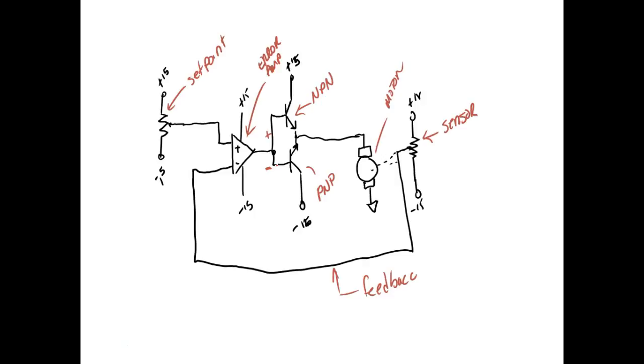The problem is, and we'll talk about this later on, we're using what we call proportional feedback. The problem with proportional systems is they have a tendency to oscillate. Why do they oscillate? Well, we turn the motor on, the motor starts spinning. The motor can't stop. It's got inertia. So it goes past. When it goes past, it says, okay, you passed, and turns on the other direction. The motor comes up, it's got inertia, goes the other direction. So the problem with proportional controls is they have a tendency to oscillate. You'll see that here.